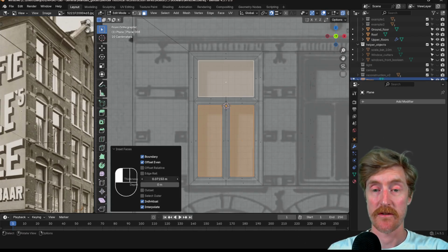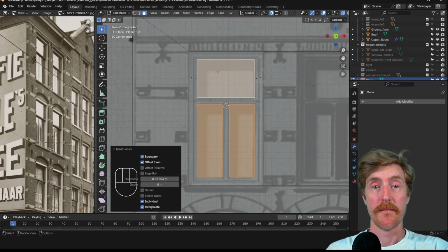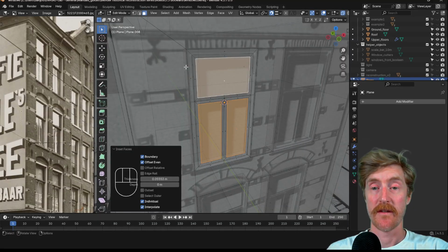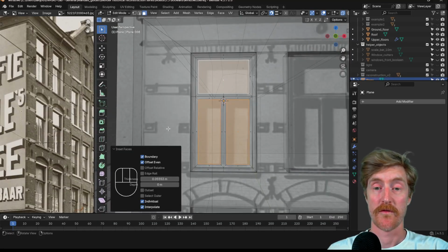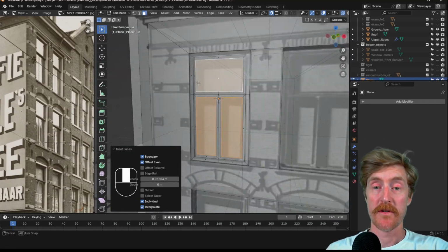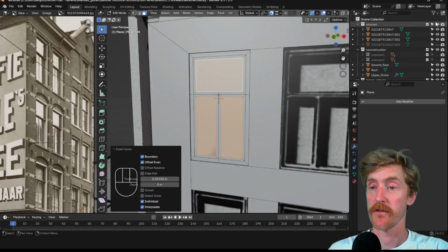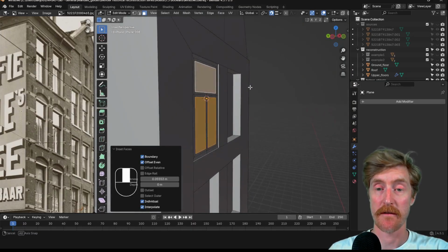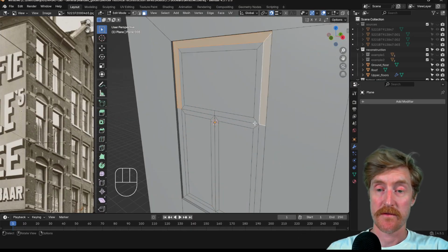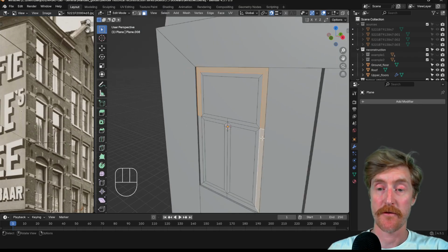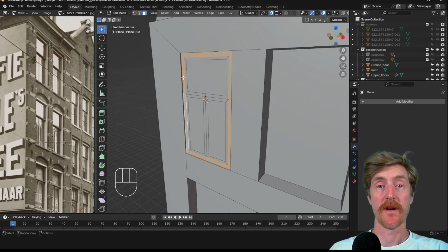And then we can still modify the thickness of these. So basically we have now created the partitions necessary to model this window frame, but it doesn't have any depth yet. So as you can see, and I will turn off the sources again, everything is very flat. This frame, the larger frame, should come a little bit in front of the recessed frames of the individual window panes.